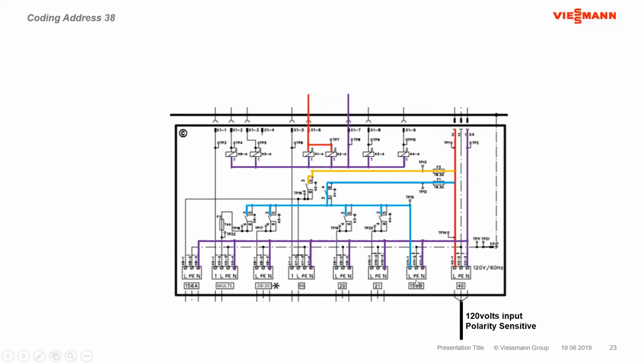So typically you might use a step-down transformer or something when you're wiring zone valves. That would be acceptable. Some of that on the 156B. It's available there for you to use. And of course, the power is now sitting at all these other relays. So we're just waiting for this boiler pump to run.